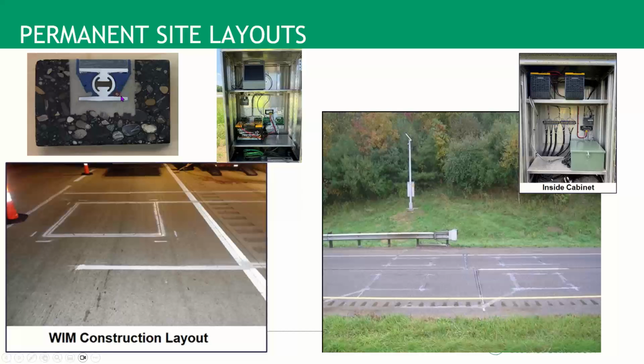So this is the grout. Again, the actual sensor works really well for a long time. It's the grout usually. The pavement will get a little crack in it, then we'll get a crack in the grout, and then we'll get a crack. So that's generally how we degrade these.